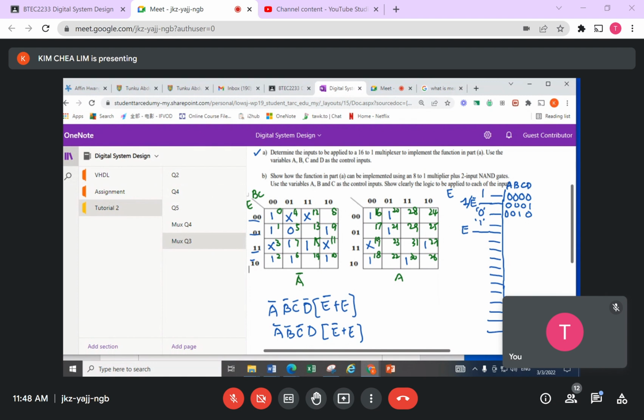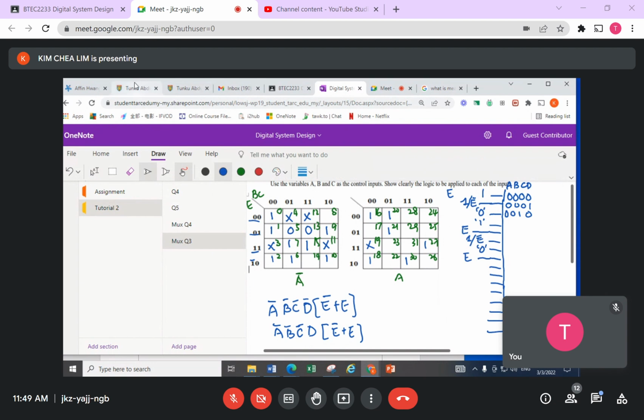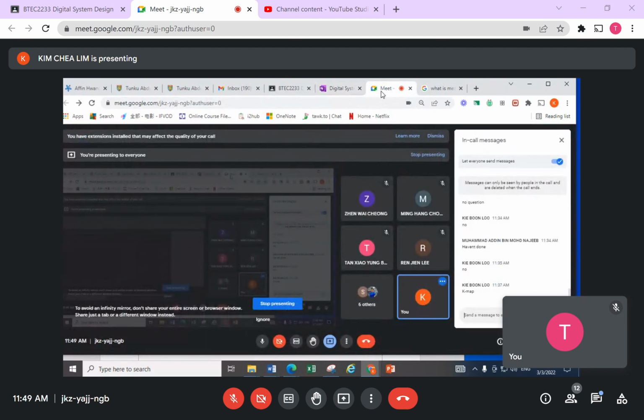This one we can choose freely: either the answer is E bar or 1, exactly the same as this. Either E bar or 1 for this case. This one here is don't care, and this is a 0, same condition, so the answer is definitely 0. All right, definitely I'm going to take 0. This one here, the answer is E. Okay to all? Anyone got any question to ask about this part?